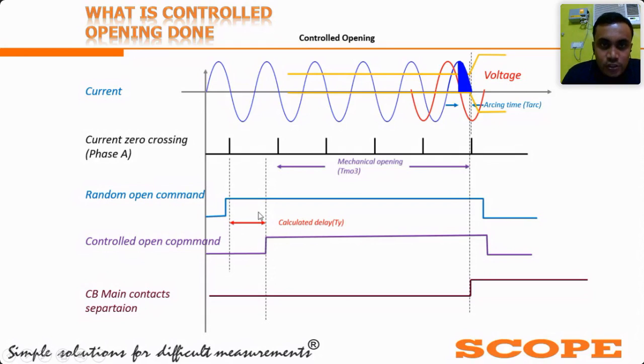Actually, for voltage peak opening, I mean to say, at voltage peak, when current becomes zero, only in that condition will no arcing or re-striking occur. To perform this, the CSD will calculate by traveling back from here, because this is our desired condition: here the current should be zero.